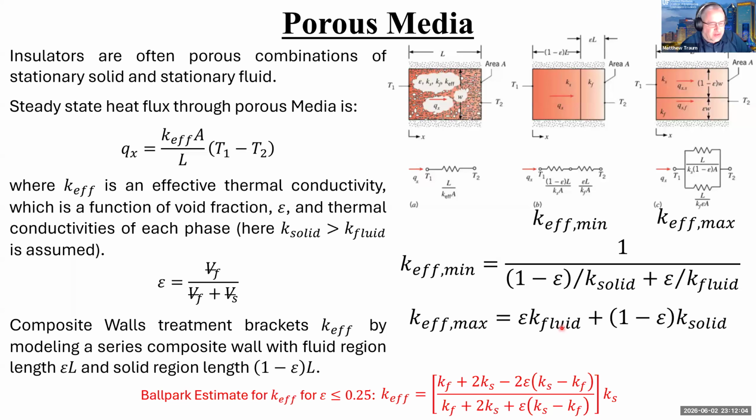So I'm using the equations that are given in the book. So that's why this looks a little weird. They're not actually resistances. They're 1 over resistance. They're conductances. But same idea. So I'm adding them up here because these are in parallel. So I'm basically adding two heat transfer paths. And then here I'm treating them in the denominator because they're two heat transfer paths that are in series with each other, right? So that's why these are reversed, conductances instead of resistances.